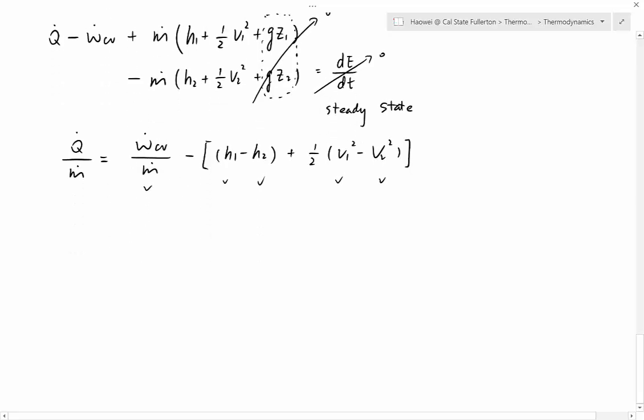But when you deal with a long equation like this, with so many different variables, what you need to do is convert everything to SI units. Then you will never have trouble. W dot CV over M dot is given as 540 kilojoule per kilogram, so convert kilojoule to joule by multiplying by 1000. We should plug in a positive number because the system generates work.